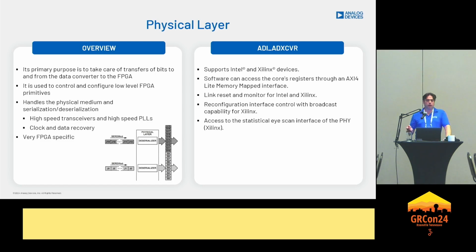The core typically handles the reset sequence and the sequencing for many things, and the reset sequence on those transceivers is actually quite essential. We also add reconfiguration capabilities so that you can change the PLL, CPLL, QPLL kind of things on the fly.